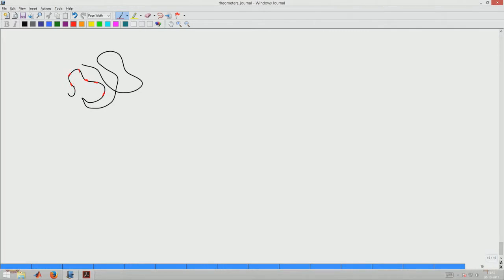But if I take this polymer to below glass transition where it becomes frozen, then the dipole orientation will not be possible. So, therefore, I can magnify the properties or simultaneously study two different aspects of the material behavior. In fact, one other thing you can do is, if you look at each and every dipole, if you add all the vectors together, in the end you can get the end to end distance, right.